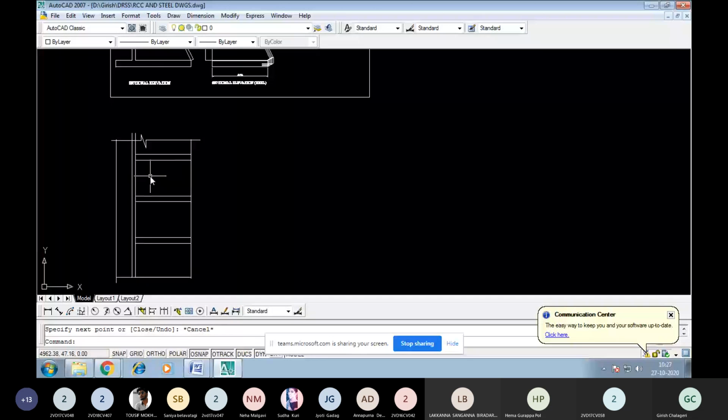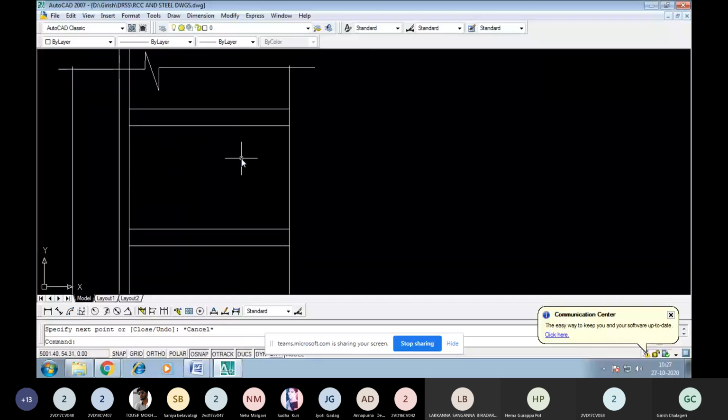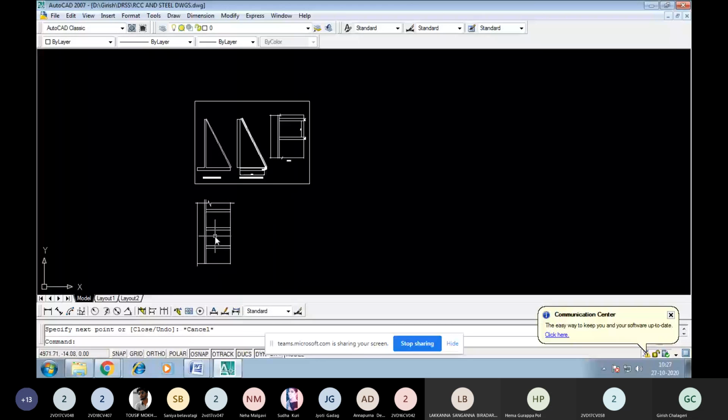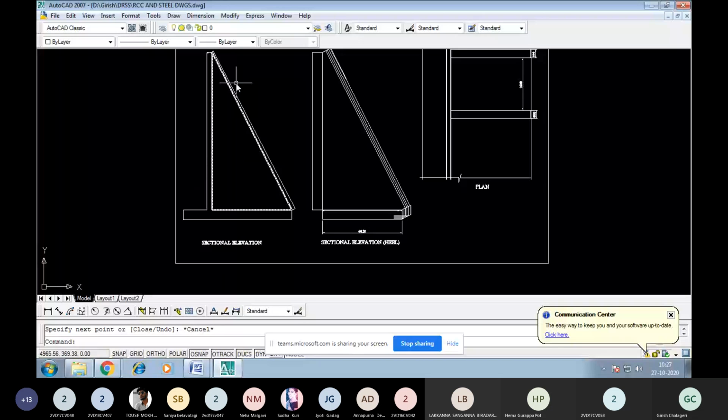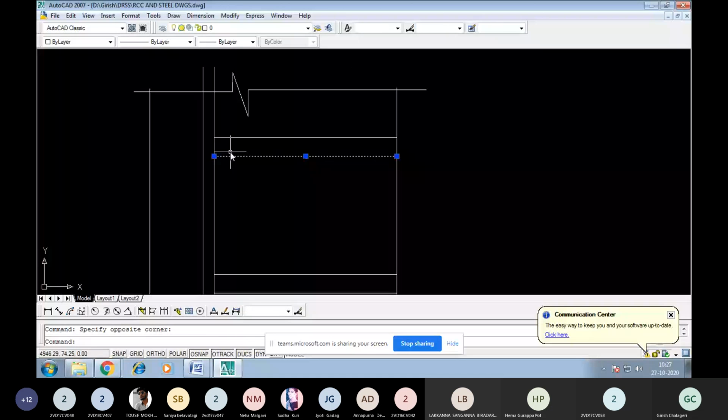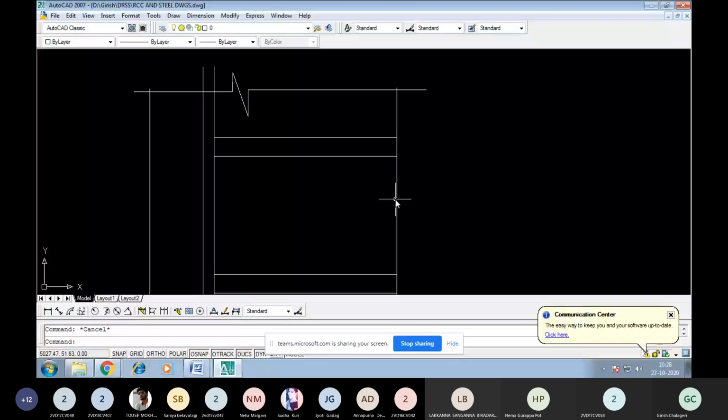What happens if this acts as a counterfort? What is the advantage here? When the height of backfill is more than 6 meters, or 7 meters, or something like 8 meters, since this counterfort is connected with the stem and the heel, the soil pressure acts in this fashion.